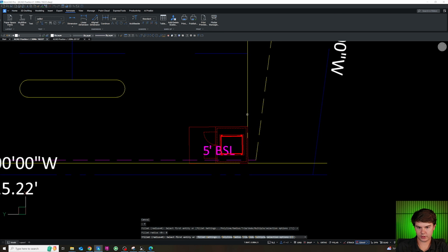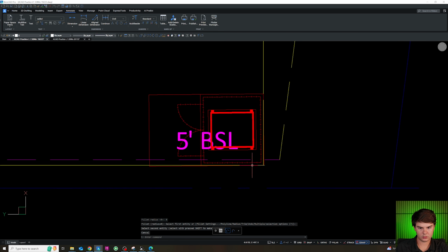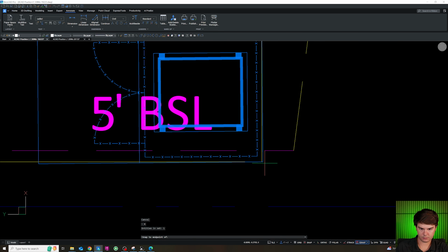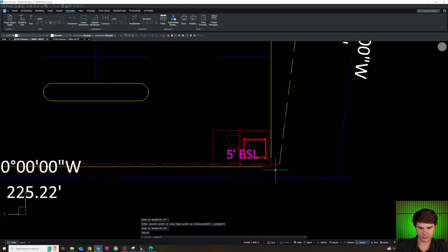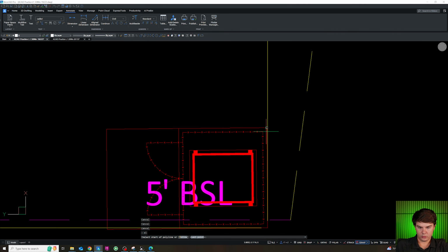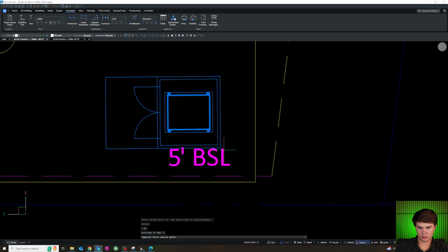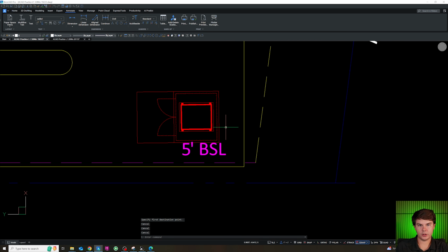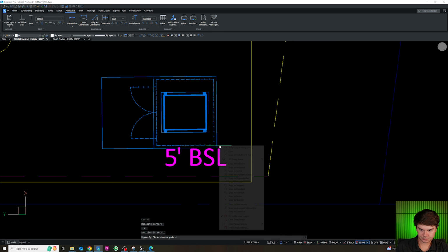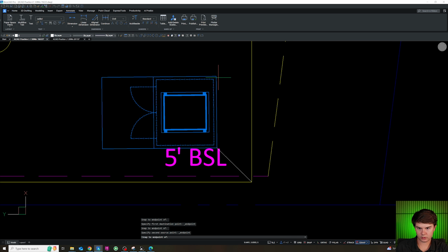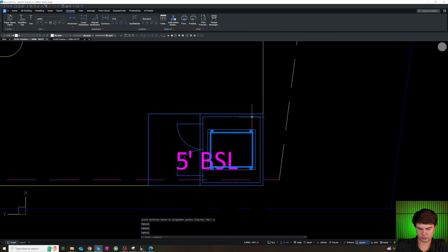We're gonna give this a radius of 0. Now that is in the corner. We're gonna have this go up. This looks a little crooked, so I'm gonna align it using the align command. Snap this to this corner, this to here, space, and no, we do not want to scale. Now this is perfectly aligned with this.